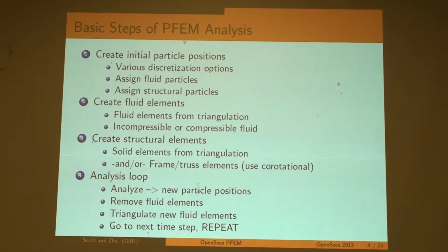So the basic steps of the PFEM analysis: create an initial discretization of particles, and the particles are where we track velocity and pressure. So that's kind of the state of each particle. Okay, and we assign different particles for being in the fluid domain, and particles that are nodes within the structural domain. Okay.